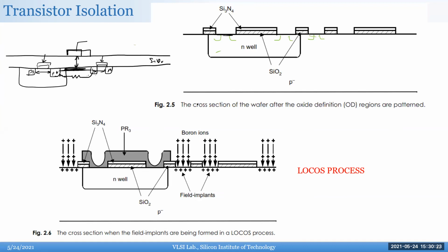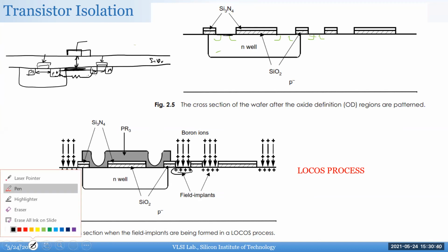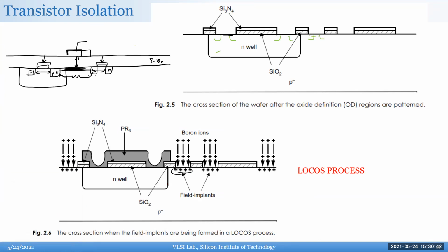That's because that's how the process has designed those devices, by doing all this process engineering. Now what you want to do in between the devices is the opposite. You want to implant these things in such a way that even if I put 100 volts, this channel doesn't turn on, because this also looks like a channel.